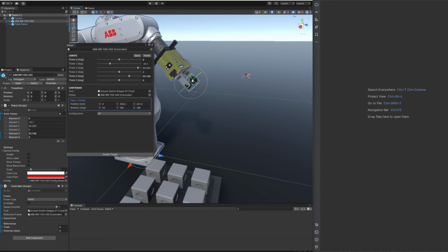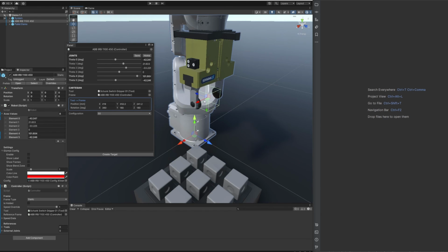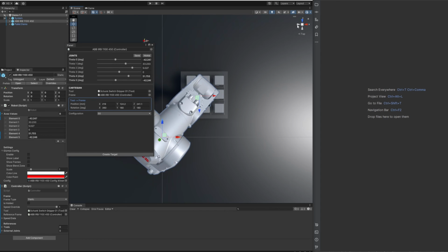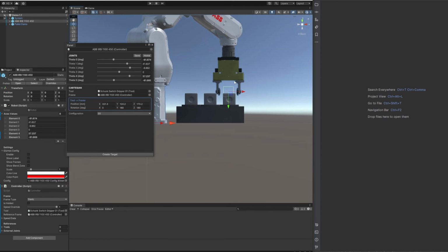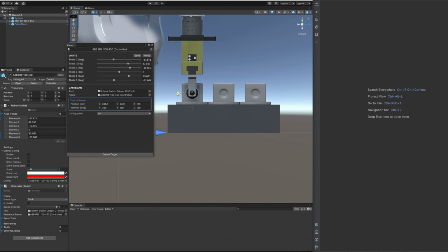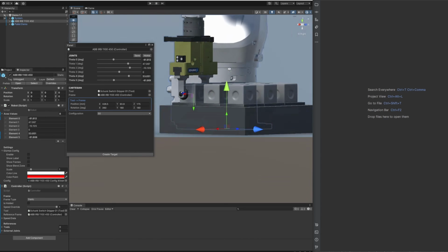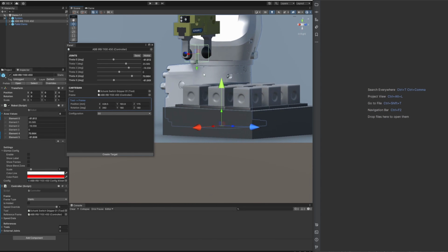I use the robot panel for this, with which the tool's center point can be moved to the required position. For the target point, I choose the box in the corner of the palette. I make the small adjustments so that the grab point is located in the center of the cube. I move the robot 100 mm in height to avoid collisions between gripper and parts.